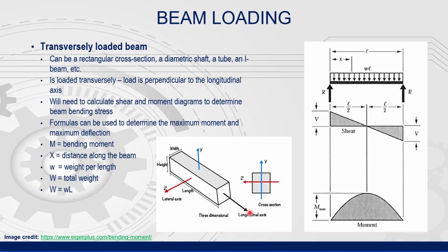The load may be a single point load, a distributed load, such as this one shown, or a combination of loads, or even a load that is offset from the longitudinal axis, but still connected to the beam. The loading causes the beam to bend relative to its supports. The loading also attempts to shear or cut through the beam. Depending on how the load is applied, there may also be twisting, that is torsion, on the beam.